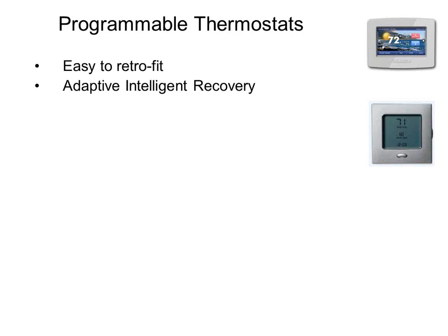Right? But if it's really cold, it's minus 10 this week, you know what, I'm going to have to start an hour and a half early in order to get you to set point by 8 o'clock. So what it allows it to do is flex the start time depending on how cold or how hot it's been outside lately. And that does save you a little bit of energy each day. It's probably only hundreds of dollars a year total, but it's hundreds of dollars a year for doing nothing. For a stat that costs like $5 more.